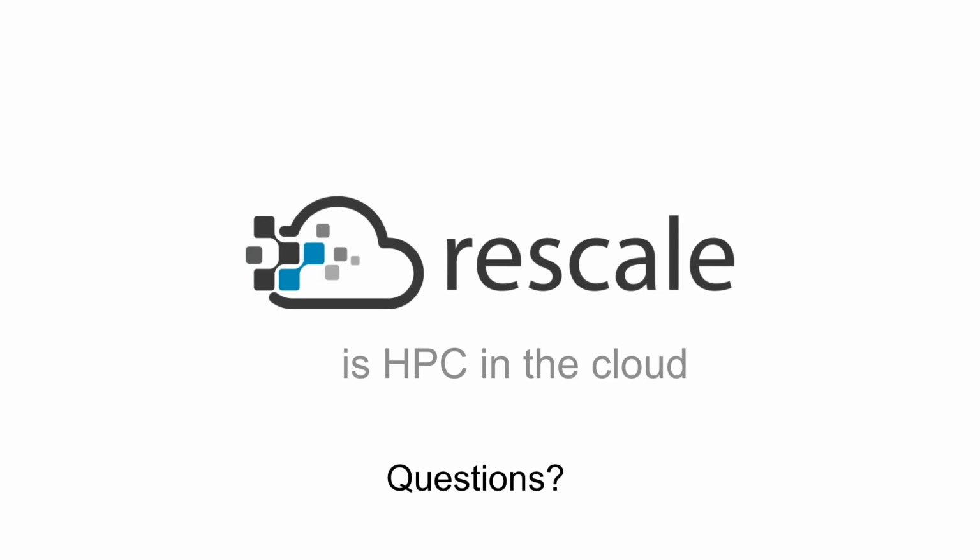But we've been working on parallel scalability, and what's important to look at is the number of mesh points that every core is in charge of. Now, the limit has become lower and lower. As of today, even if you have a load as small as, say, 30,000 nodes, you still perform pretty well, which is good news. So even if you have, say, a 200,000 mesh, you can still scale and use a node, and the scalability will still be okay.